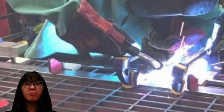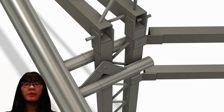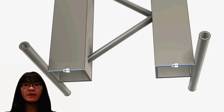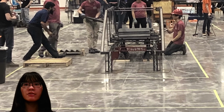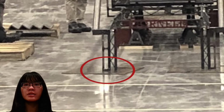As with most analysis, there are limitations to our analysis in Fusion. Fusion models all of our connections as welded connections, while in reality, many of them are pin connections. In addition, the way the analysis was performed was that each leg was fixed on the side facing into the bridge. While this was to make sure that the bridge's legs would not deflect into the ground, the bridge's legs in a real-life situation would not have been fixed and would be free to slide on the ground when applying loading. But Fusion would not allow a simulation to happen without fixed constraints.